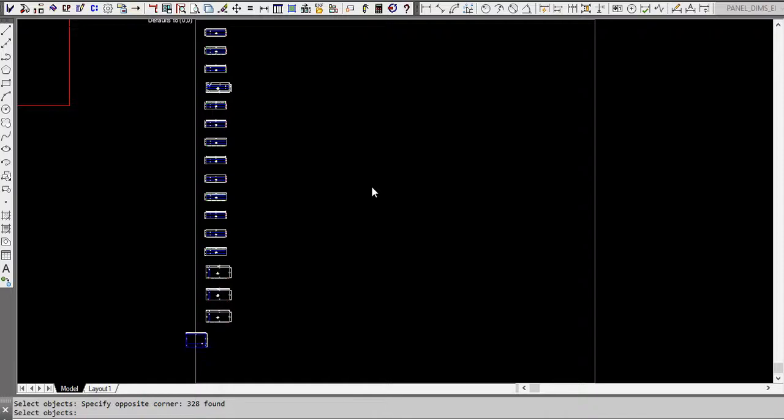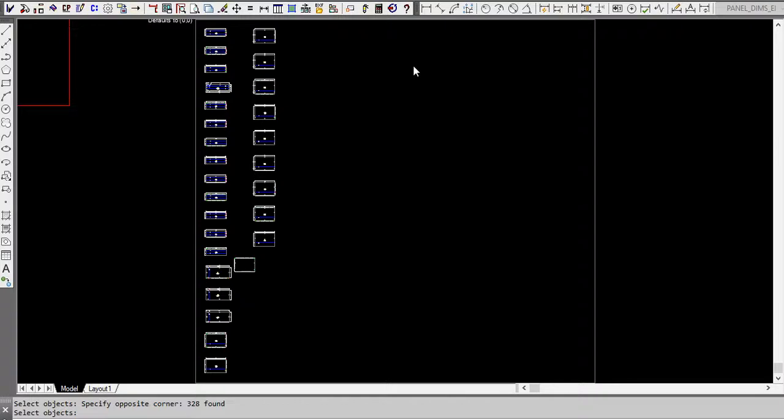So we're 29 minutes into this video. Once you've recreated a panel inside the work area here, anything that's left inside this work area gets deleted. So you have to be careful. If you create something, you either want to stage it or move it out of here so it doesn't get deleted.